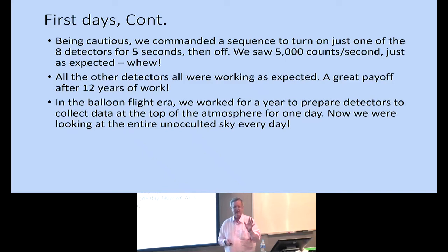Now, we don't send back high rate data all the time, we can't afford to do that. We're actually looking for signal rate increases in 2 or more detectors. We capture data at a high rate for a couple hundred seconds, and then dribble that data back over the next 90 minutes while in orbit. So we're capturing the data all the time, but we're looking for triggers to capture high rate data and then send that data back.